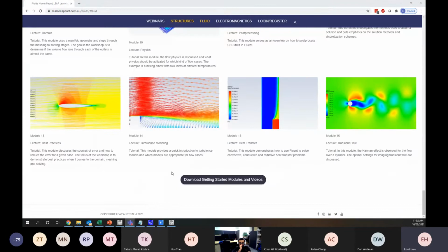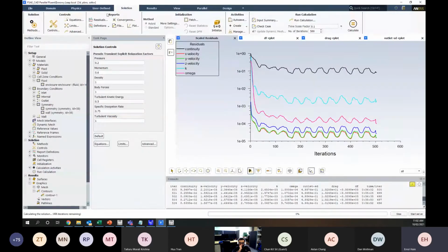Okay, so SBES, stress blended eddy simulation. How do you create the downforce, drag, and outlet SD? We've been through that. So if you go back through the video, you'll see it, but it's just in here. So definitions, specify a definition for a force or for a standard deviation or a pressure value, vertex average, vertex minimum, volume average, things like that.